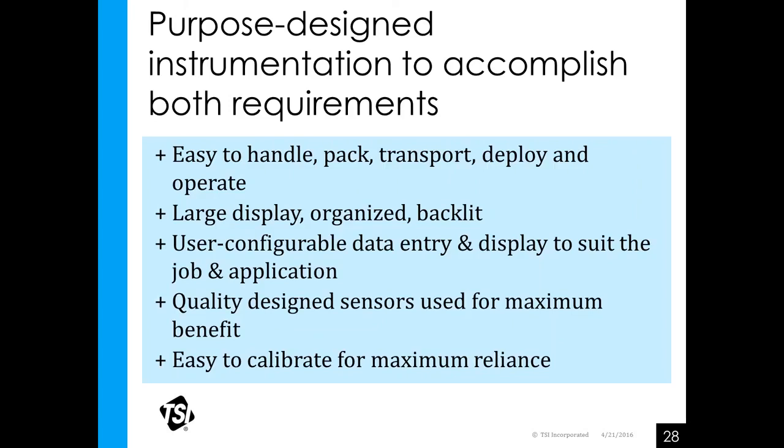The calibration certificate refers to the probe and the sensor itself and not the meter. Years ago, any offsets or adjustments in the sensor and probe's performance needed to be stored in the meter. Today, the best sensors are smart, meaning any offset, any readjustment of performance to bring that sensor back into true calibration is stored in the probe itself.